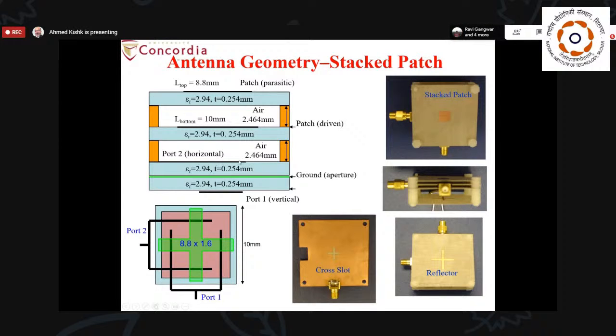So between this microstrip line and this line, they are isolated by the ground plane between the two slots. In order to improve the matching, we made this coupling through a fork type of microstrip line excitation, and this is also a fork type of excitation.